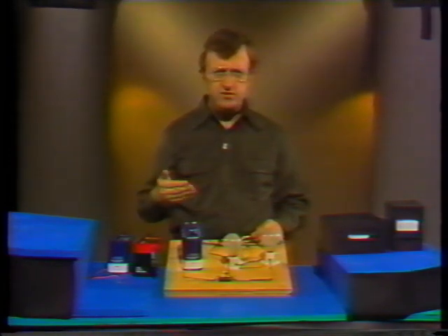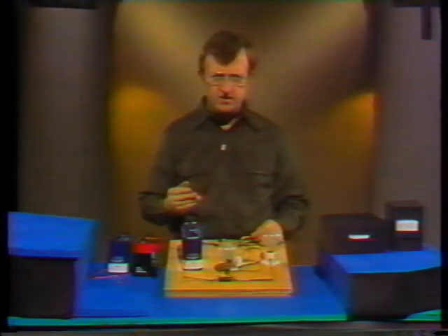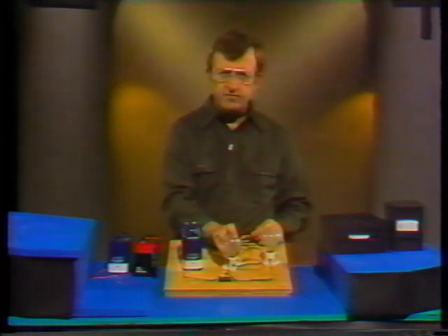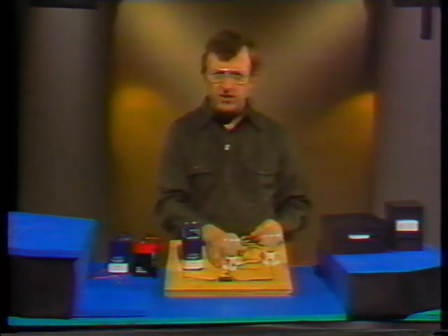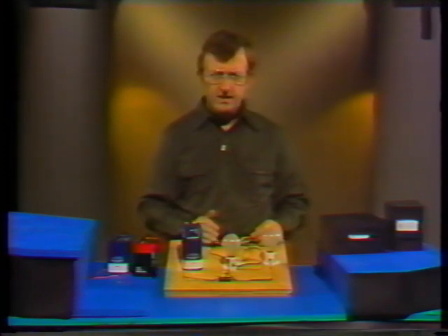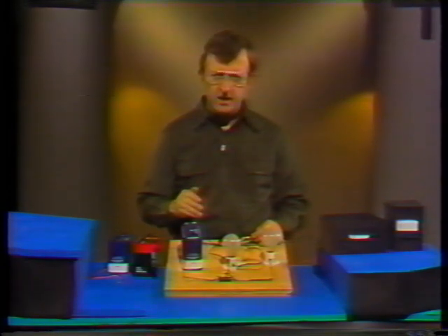We can also assume that if the voltage remains constant, the greater resistance we have in the circuit, the lower the current flow will be, and vice versa. We can go back to the formula we used earlier to show how current and resistance affect each other when voltage is constant. According to Ohm's law, current equals voltage divided by resistance. I equals E divided by R.